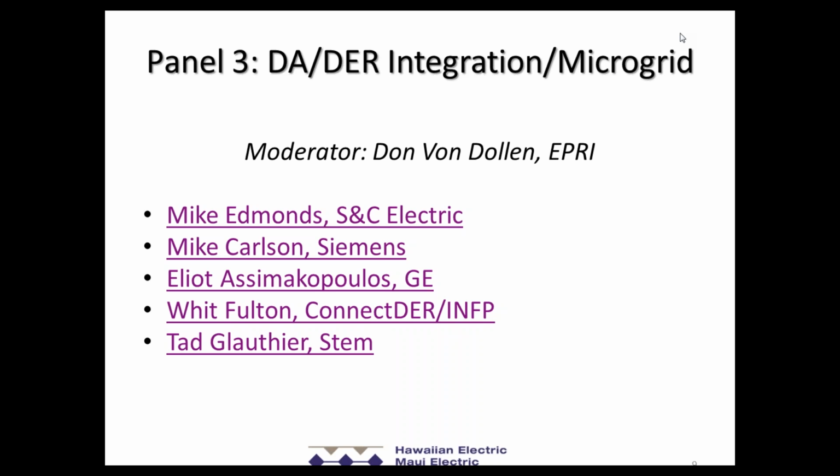So this is where I show some of my geek side. Mike Evans here from S&C. The traditional grid has fuses in it. In fact, as you well know, your fault levels are falling as you take rotating machines off. So you're going to need to change some of the types of lateral protection you have to make sure they're programmable so they can change over time. But you also have some new technology you could deploy. For example, those smart switches I showed actually have the ability to change protection curves in real time. So if they detect a fault, they can get greater discrimination